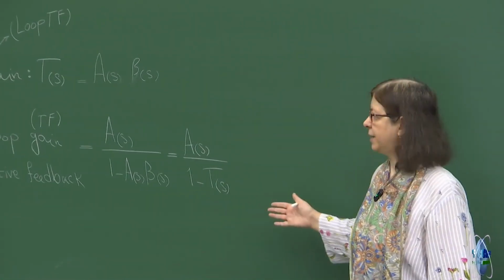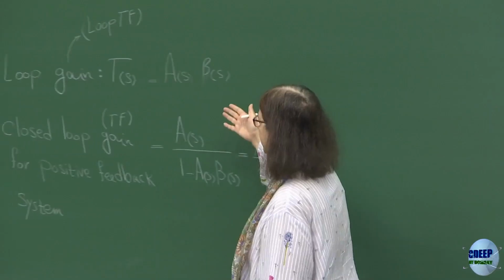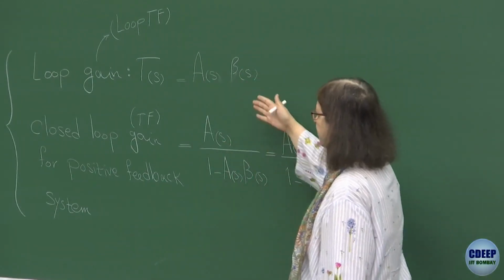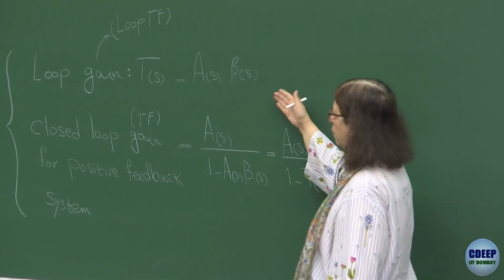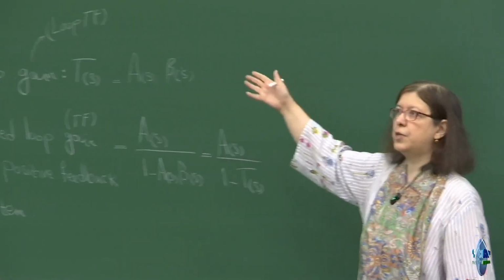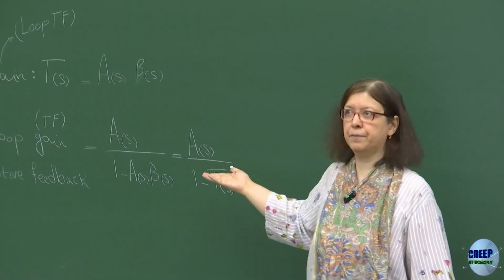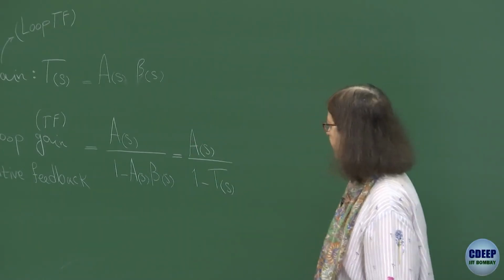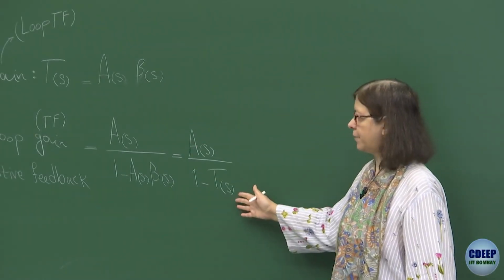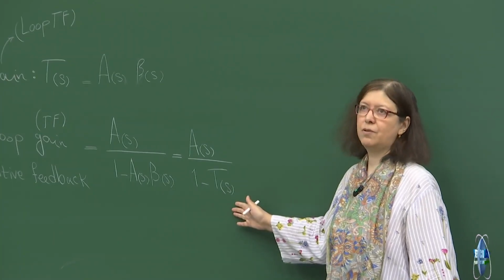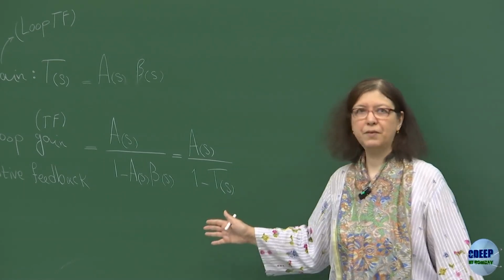Therefore, either you go with the first method and derive the loop gain in the loop, naturally without any input, and when you go one round in the loop, you get back to the original point, so the ratio of the two variables should be 1. That is equivalent to saying T(S) equals 1, which also is evident from the closed loop transfer function, and gives you the poles of the closed loop transfer function. Fine? So this is just for clarification.